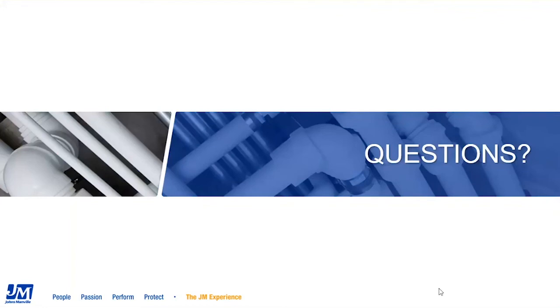Excellent. The next question is also for you, Meredith, and that is, when should I use flexible elastomeric insulation versus fiberglass? It will depend on the application. If you are insulating sections of pipe that are curvy, you will need a flexible insulation, as our fiberglass pipe sections are rigid and are intended for straight runs.